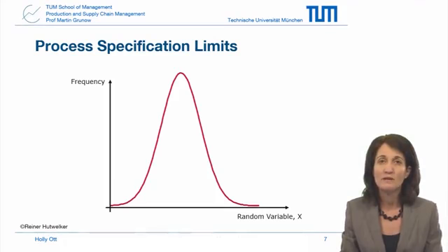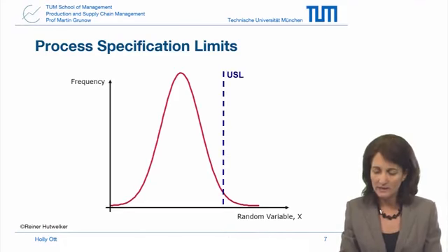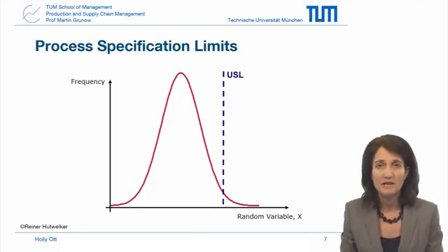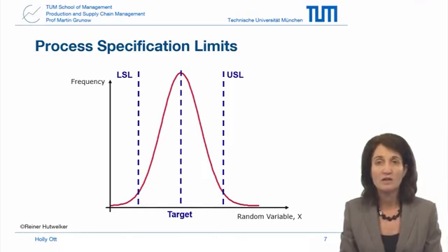And for one single normally distributed variable, we can consider an upper specification limit, or USL, and a lower specification limit, or LSL. And the process target then would be centered at the midpoint between the upper and lower spec limits as shown here. And what we have here, of course, is that the mean of our actual variable is centered according to the target.